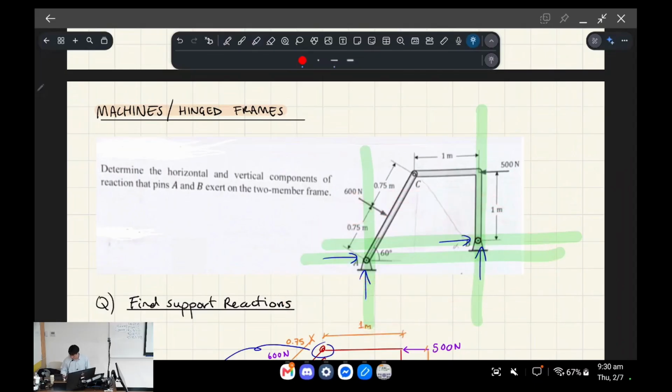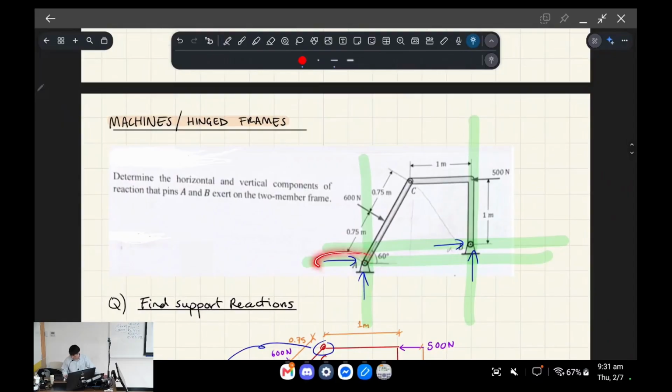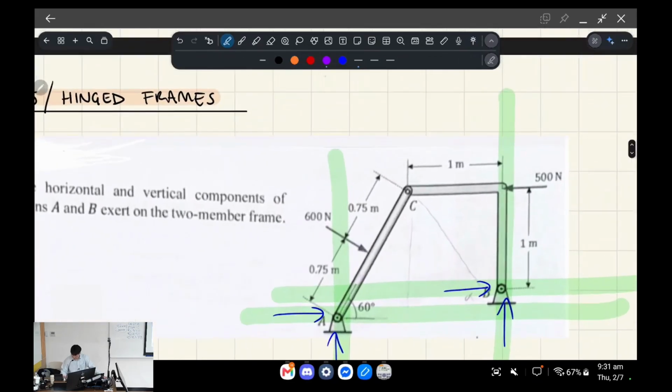And the other thing is we've got this kind of diagonal load on it. And so if we analyze the overall frame using the methods that we've learned over the course, we're not going to be able to solve this normally, okay? There's too many unknowns basically, right? And we're trying to work out these reactions essentially, right? So we need to introduce a new method, and what we have to do is realize that this frame is actually split up into 2 separate rigid bodies.